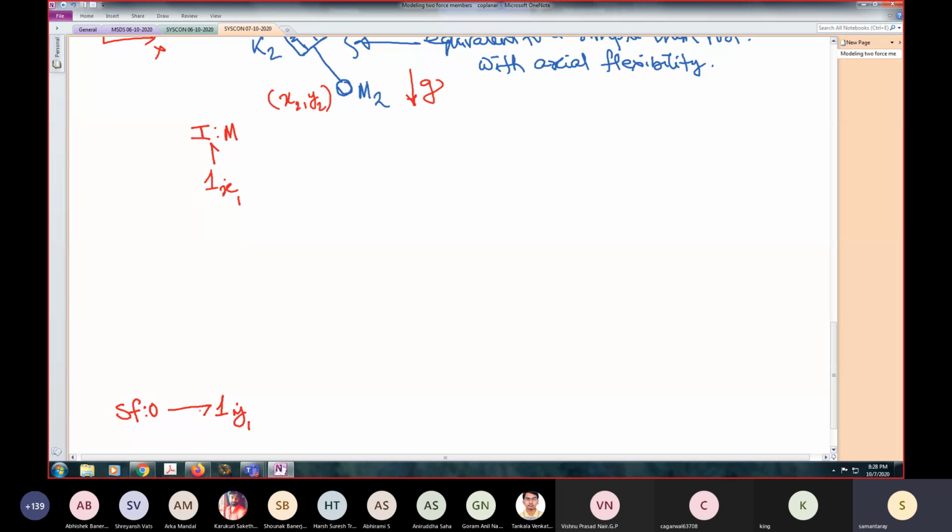I have seen in your assignments, some people put source of effort, gravity, in x direction. I have seen interesting bond graphs. Everywhere mass is there, there is weight. No, it has to be only in the y direction. And here, because in y direction we do not have motion, that block is constant in y direction, so we can remove this y1 dot junction afterwards. So right now I have kept it.